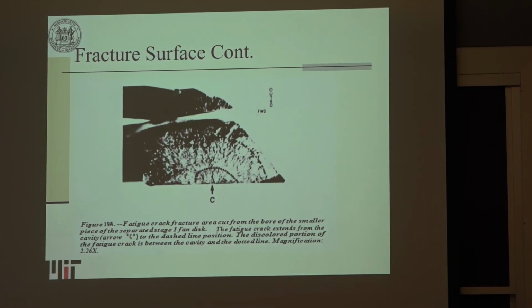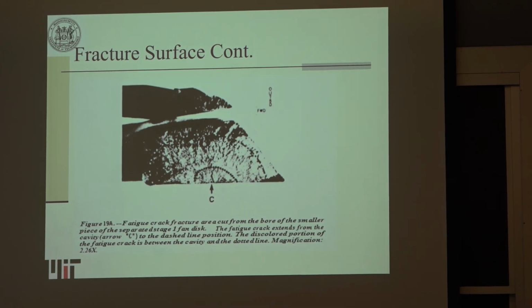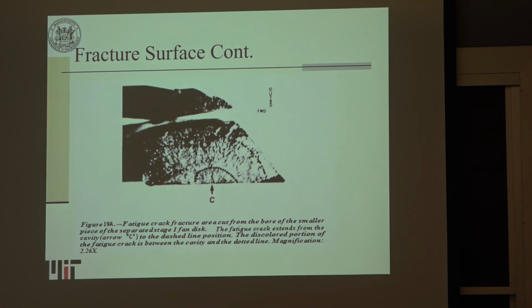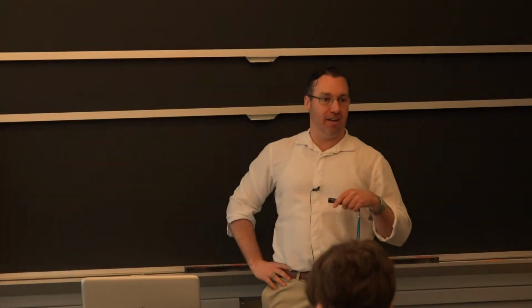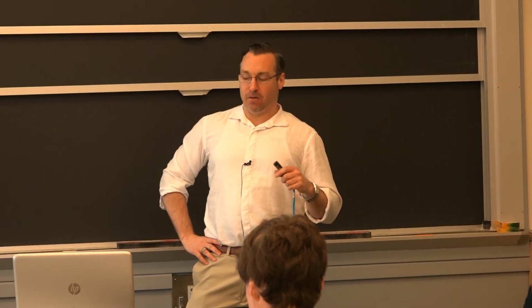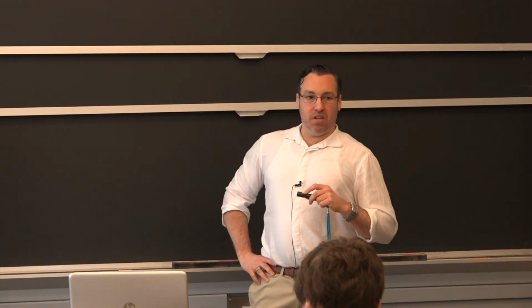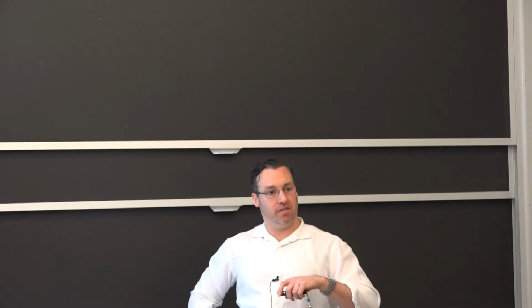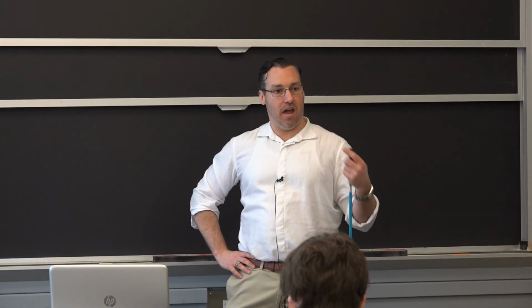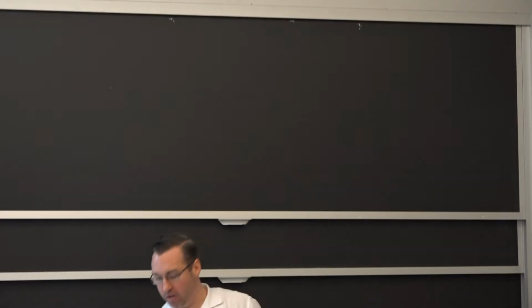Any way to tell the time? Yeah, they can estimate if they go to a high enough magnification, because it's cyclic, they can see striations, and you can see cycles. But trying to back calculate an exact number of cycles is difficult. It's easier to just go into the maintenance logs and the operating logs, because they'll keep track of the hours the engine's been running that way.